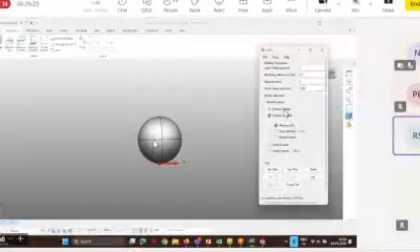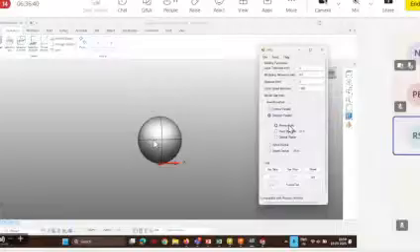Then you can select the tool path. Here you can see we're using direction parallel, which is nothing but a zigzag, but zigzag with minimum lift. We have put in some of our own logic so that we calculate whether the number of lifts is optimized or not. If it has more lifts, then we rotate the zigzag angle in such a way that we keep going until we get the minimum number of lifts. So like that, we can specify over here.